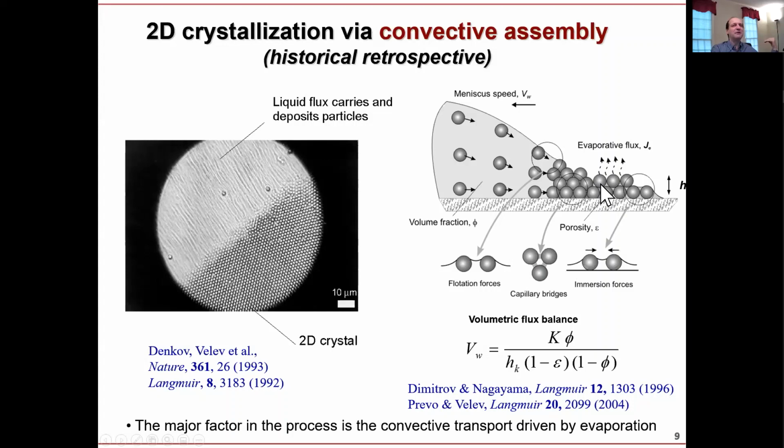Essentially, the capillary pressure would create, if you start evaporating liquid from a crystal, the meniscus here is going to go below the surface of the beads. And when it does, you're going to have essentially a negative pressure because of this high curvature. And then it is going to be drawing new liquid from the meniscus. So this under pressure in this case is capillary pressure.